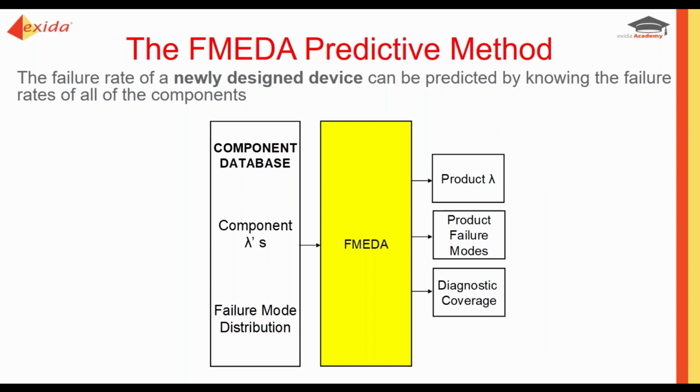So let's take, for instance, a bolt. A bolt's pretty easy. How can a bolt fail? Well, a bolt can break, it can shear, or a bolt can loosen. So for both shear and loosening, we have the chances of that bolt shearing or loosening. Then when we look at the FMEDA, we look at that bolt in the device itself. So if that bolt does shear, can the device still perform its safety function? Can it still do its job? Or is it going to be prevented?